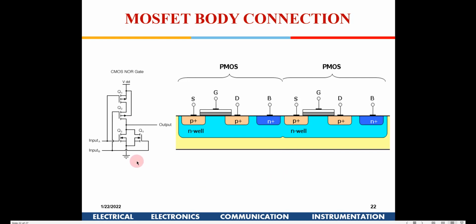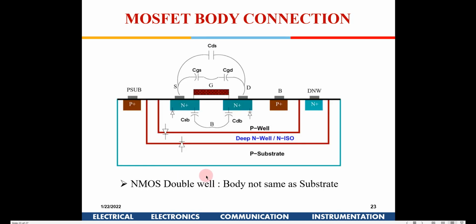Obviously this transistor might have a body effect, so there will be some VT increase, because they are not at the same potential. In case there is some critical circuit in which you can't afford to have a higher VT, there will be some situations like that.